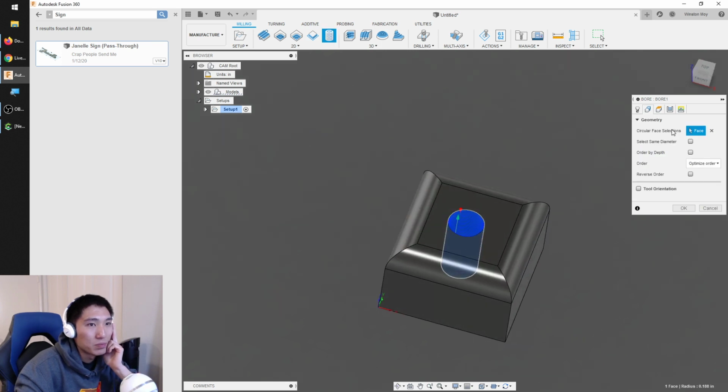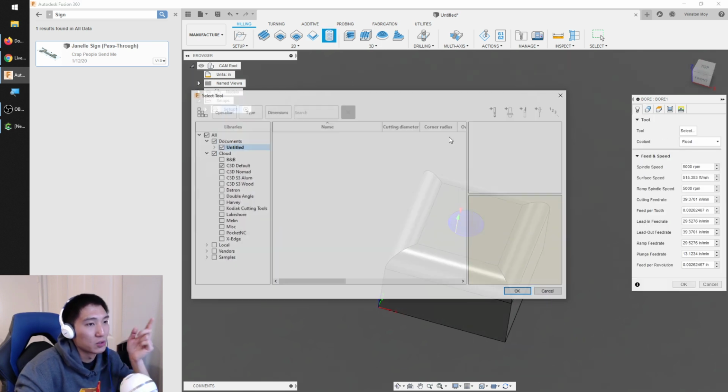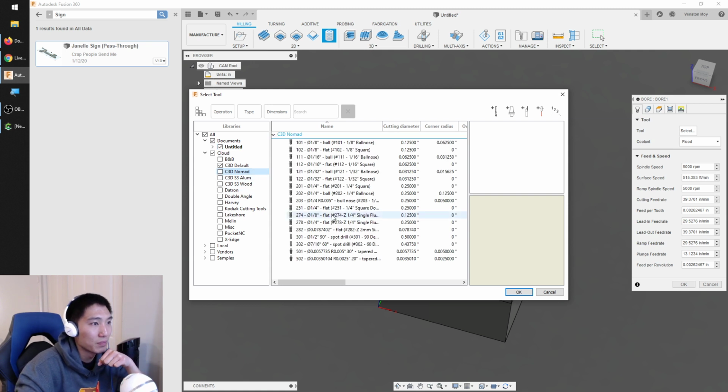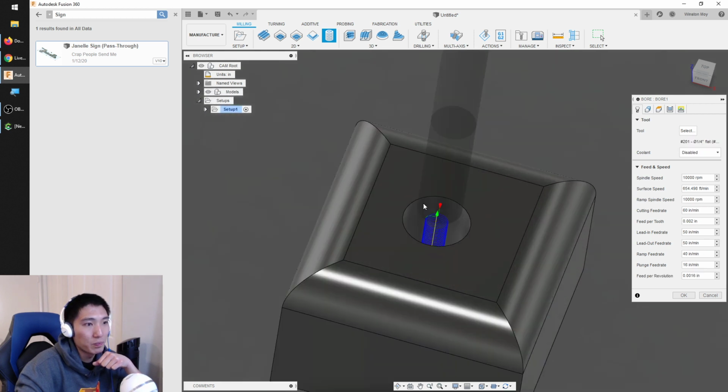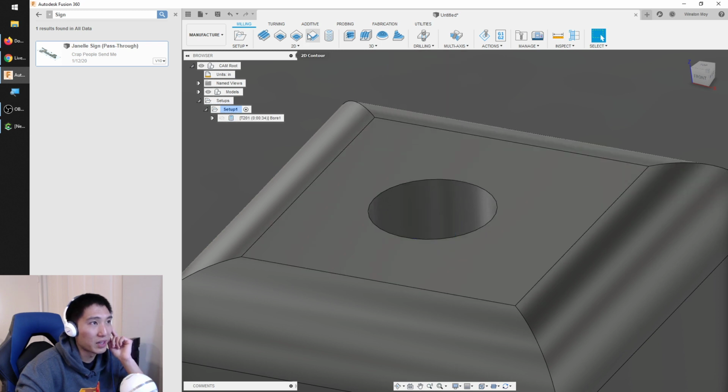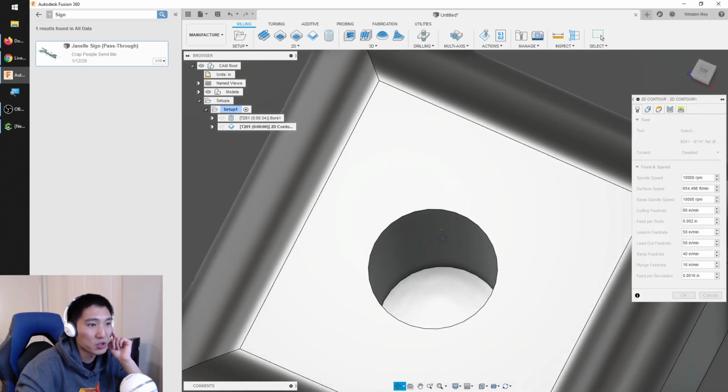And that will create a helical toolpath that spirals to the bottom, and it'll mill out an area that's wider than the end mill itself. So let's say a 1/4 inch end mill. That's what the end mill is going to do, all the way to the bottom, and leave you with whatever size hole you want. So a boring operation, or if you do it with a contour operation, that works too.